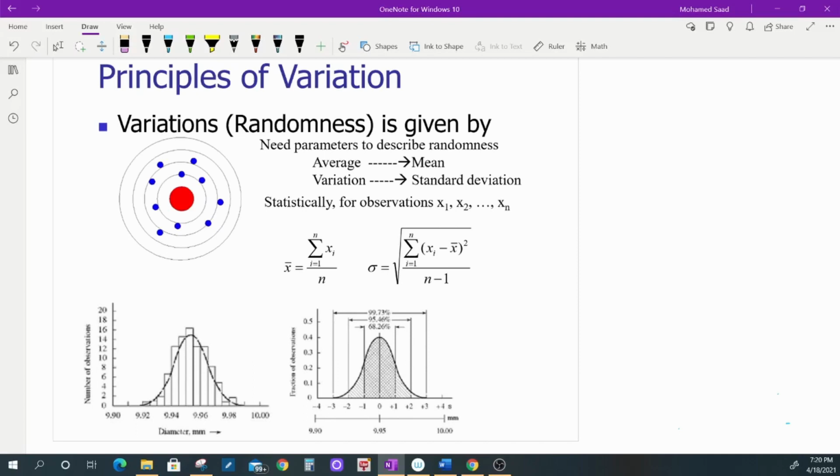So that's why, if you look at the 2D drawings of parts, you will usually find dimensions like this, like say 5 plus minus, let's say 0.1. So these tolerances represent the required variation, or the designer's acceptable variation, within which the part will still work. And it's very important here to mention that